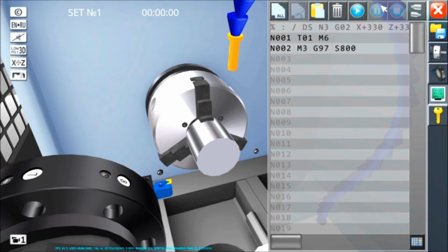Absurdly, X0 would correspond to infinite revolutions, which is why there is normally a code, which in this case is not contemplated. On the Fanuc it is G92 S2000, which ensures that the spindle can never exceed 2000 RPM, regardless of the programmed cutting speed.